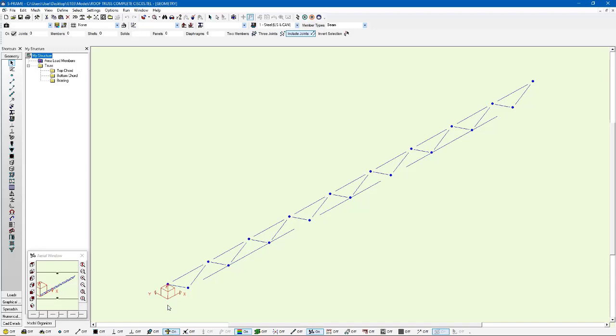One thing that we want to take in right away is that we want to know where the user coordinate system or the coordinate system origin is of our particular model that we're merging in. In this case here, we can see this is the coordinate system origin, right at the point, right below the top of this, or the bottom of this top chord here. So if I just left click on this joint right at the top chord, I can see that the coordinate is 1 meter above this user coordinate system origin.